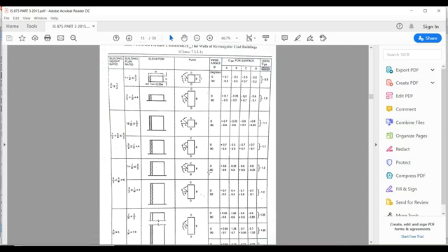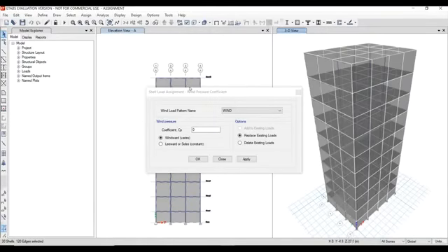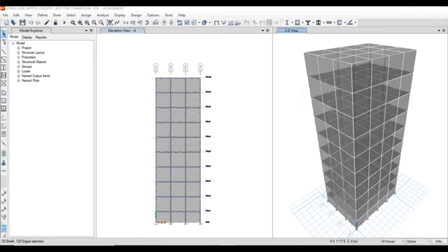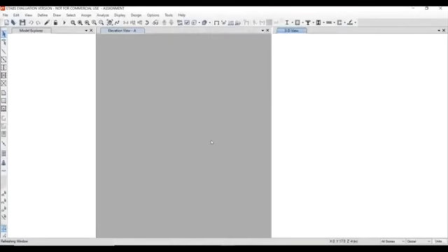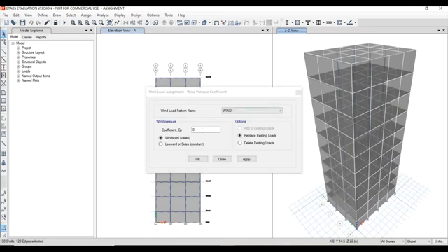So from this, at theta equal to 0 degrees, we have the coefficients of plus 0.8 in the A direction and minus 0.25, minus 0.8 and minus 0.8 in the remaining directions. So we need to enter these values in our model. So coefficient of plus 0.8 in the windward direction. Apply.